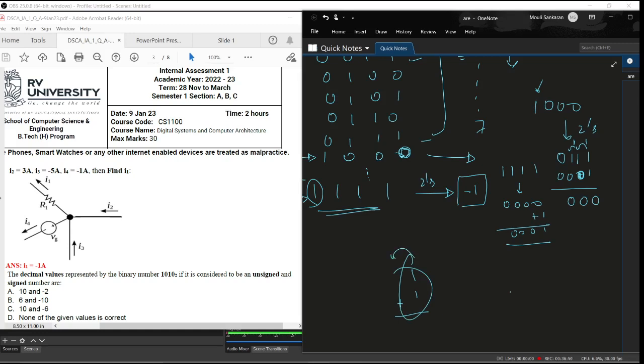Now, if you want to represent the 2, you need to take that 1 to here, because we cannot have anything more than a 0 or 1 here. So this value is basically a 2 in binary representation. That's why the carry is 1 when you are adding 1 and 1. I'm sure you will know that. So this is also 0, 1 plus 1, again one carry will come, and that is getting added with the zeros. So this is the value. Now you should compute this as a magnitude. So it is 2 power 3 plus all zeros. So it is 8. So this representation 100 gives you -8.